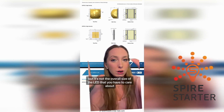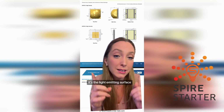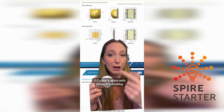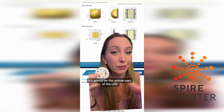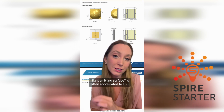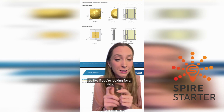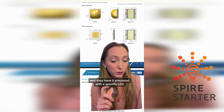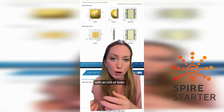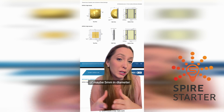But it's not the overall size of the LED that you have to care about, it's the light emitting surface. Usually, if it's a white with phosphor coating, it's gonna be the yellow part of the LED. Light emitting surface is often abbreviated to LES. You might see that on optics, so if you're looking for a lens and they have it simulated with a specific LED, then it might say with an LES of 5 millimeters, and that would be a light emitting surface of maybe 5 millimeters in diameter.